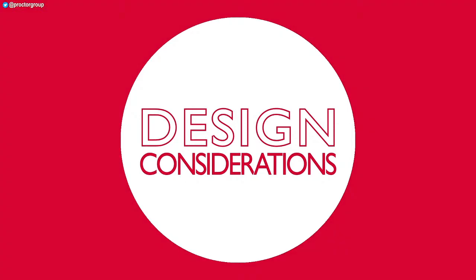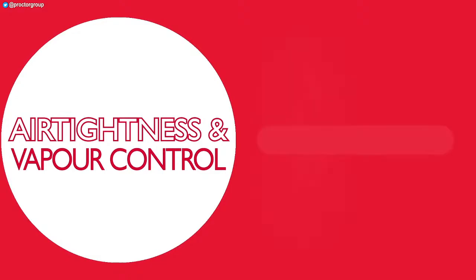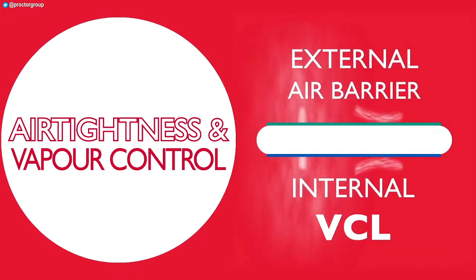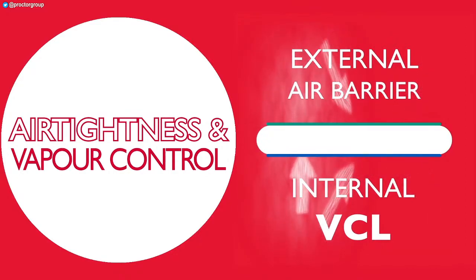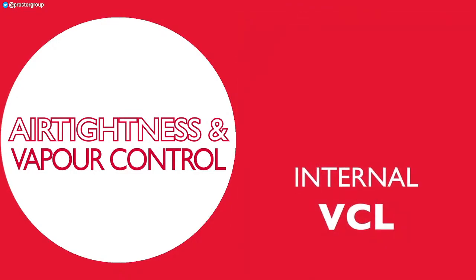The primary design consideration we're looking at here is limiting unplanned air movement throughout the building fabric, whilst reducing the risks associated with condensation and excess moisture. The most important of these considerations is where in the building element we place both our vapour control layer and our air barrier layer. Traditionally, these two functions would be performed by the same membrane, as most vapour control layers will also perform the function of an air barrier.